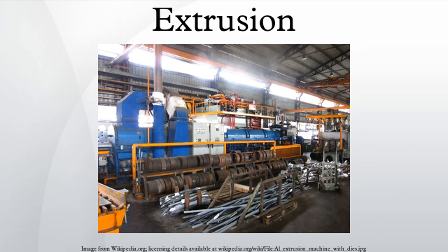The biggest disadvantage of this process is its cost for machinery and its upkeep. The extrusion process is generally economical when producing between several kilograms and many tons, depending on the material being extruded. There is a crossover point where roll forming becomes more economical. For instance, some steels become more economical to roll if producing more than 20,000 kg.